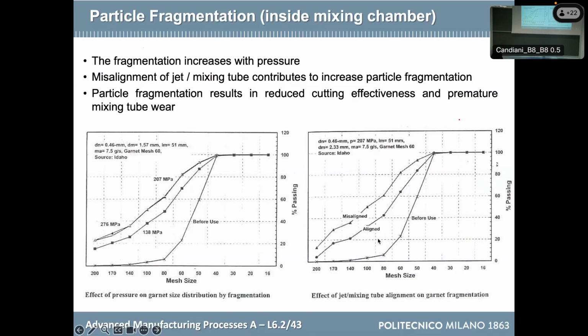But also it is interesting to see that if the orifice is not aligned with the focuser, we are destroying more abrasive because the process is not smooth. And so the abrasive hits the wall of the focuser and is destroyed instead of passing through.